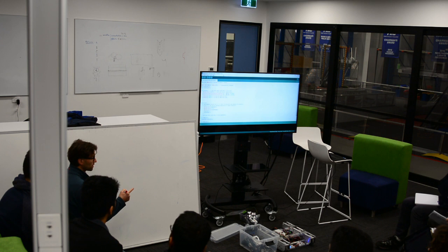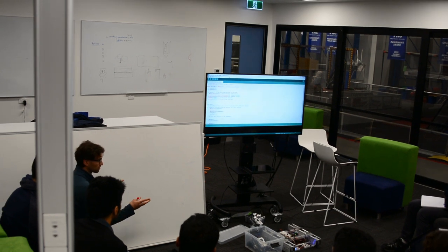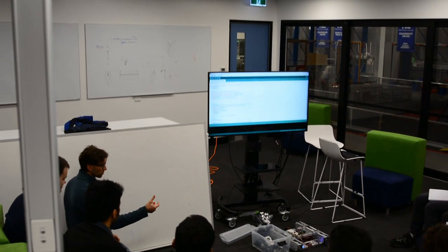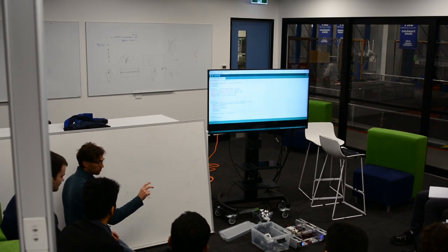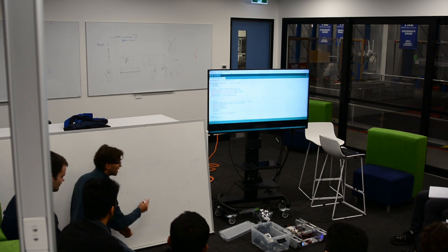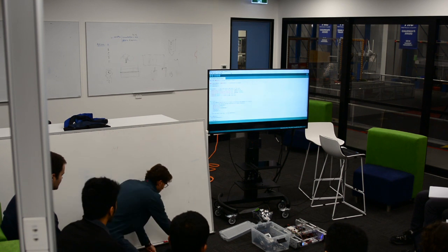The interrupt will always listen to a rising pulse. Doesn't matter what else is going on. So if your Arduino is trying to do lots of other things and the wheel turns, the idea is we don't want to lose that pulse. We don't want to ignore the pulse. So it's on what's called an interrupt, which is a high priority.